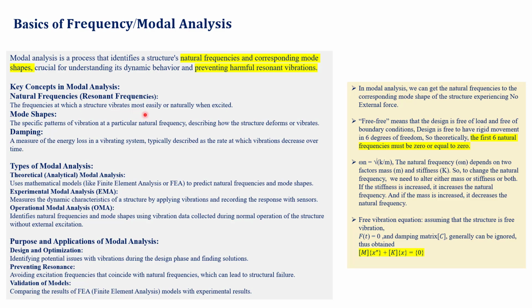If I consider the tuning fork again, its vibration along the y-axis is natural, right? Depending upon that tendency of vibration, we extract the natural frequency. So this is the importance of it. How exactly, or in what way, the structure deforms or vibrates is shown through the mode shapes.